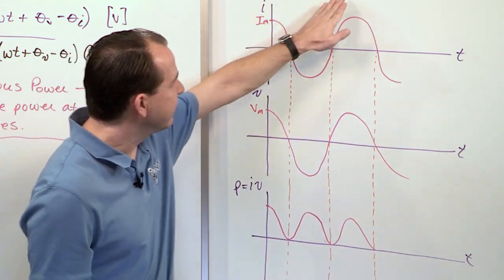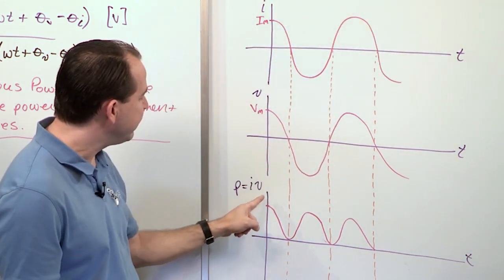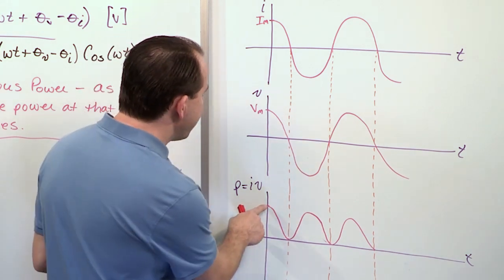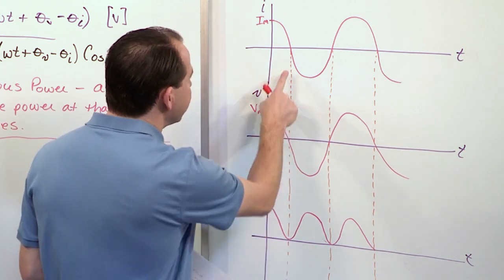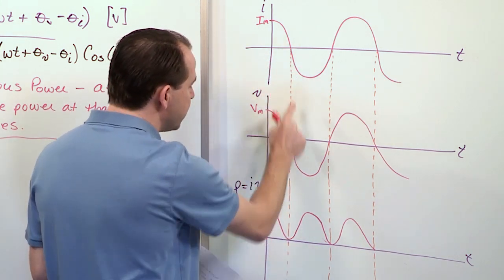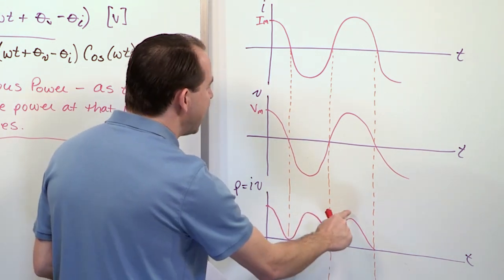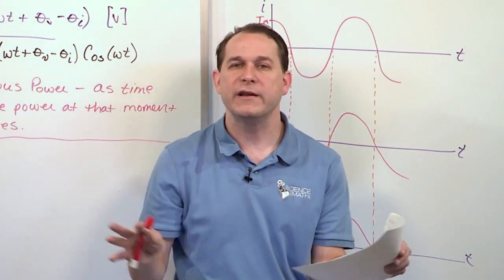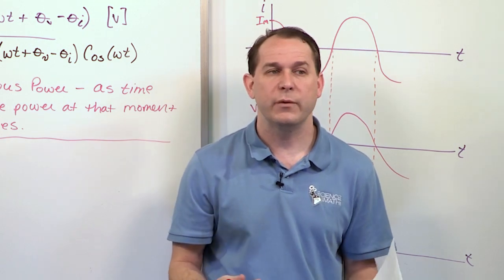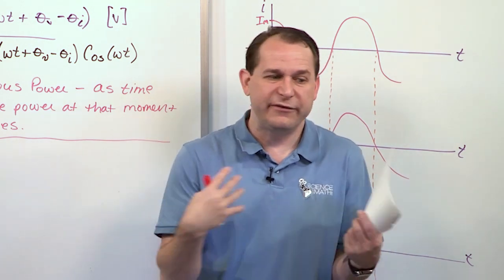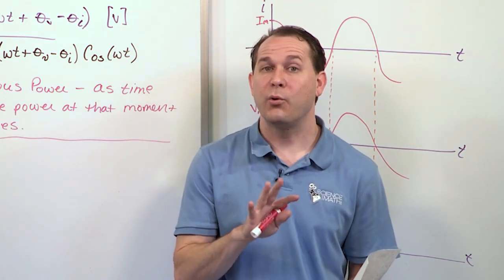That's why, in the case of a resistive load, when the current and voltage are lined up, you multiply everything out. Even in the AC case, you see the power going up and down. Of course, the power is a maximum here because the current and voltage are at maximum. The power is a minimum here because both current and voltage are crossing into a minimum, so there's less power being dissipated here. But then it climbs back up, and then it goes to 0, and it climbs back up again in accordance with this. But no matter how you slice it, a resistor can never, ever, ever store energy, so it can never be stored for later release, right? Now I'll give you a little bit of a preview from the point of view of this guy.